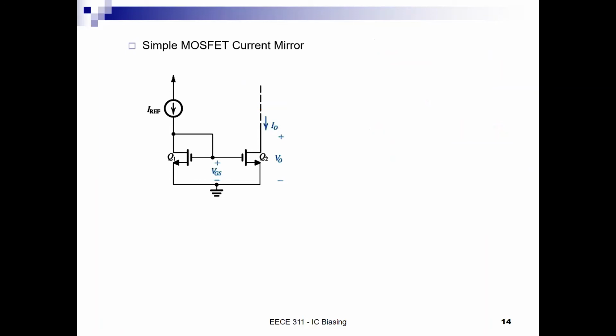Okay. So let us envision how we can draw a PMOS circuit. We should have two transistors, which are PMOS devices, and they are both sharing the same gate G, right? And they are connected to VDD because they need to be connected to VDD to source the current from VDD. Now in the PMOS, we know that the source is always the higher voltage. So we are going to connect the sources to VDD.